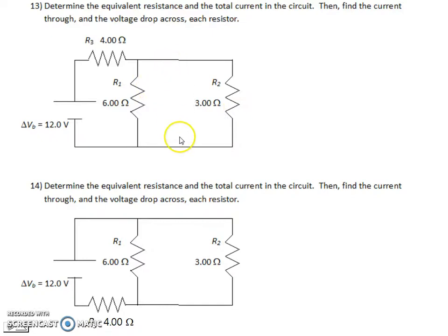And either draw it separately or just imagine it's 2 ohms of resistance, and then we say, if we take these two out, now this combination is in series with the 4 ohms for an REQ of 6 ohms. 4 ohms here, and a total of 2 ohms here. Now what can we do? Well, we've got 12 volts for 6 ohms. Now we can do total current. That's going to be 2 amps, which again I draw here coming out of the battery or going into the battery. Either one is fine, or both is fine as well.